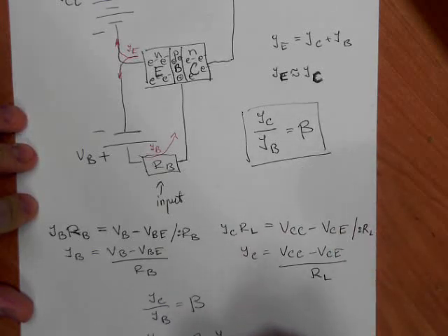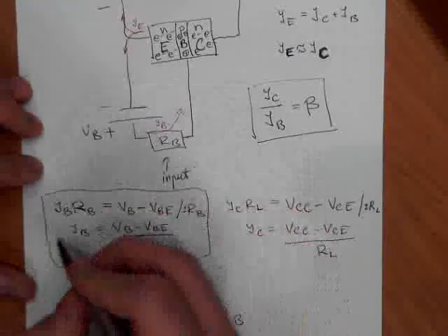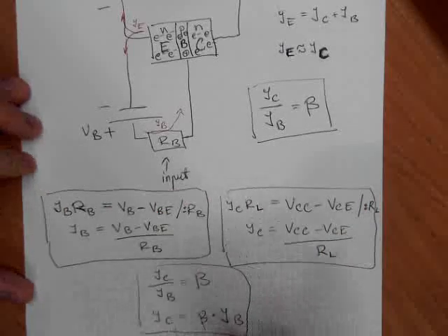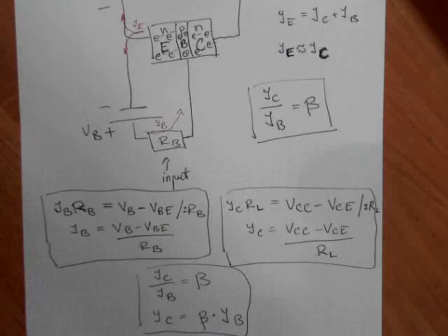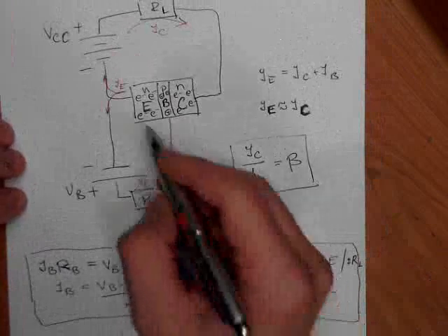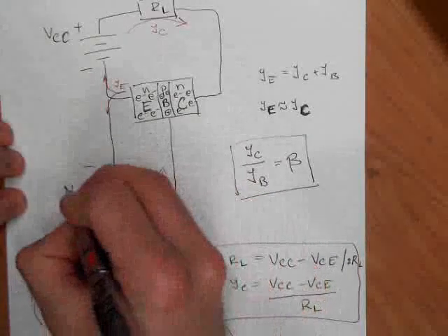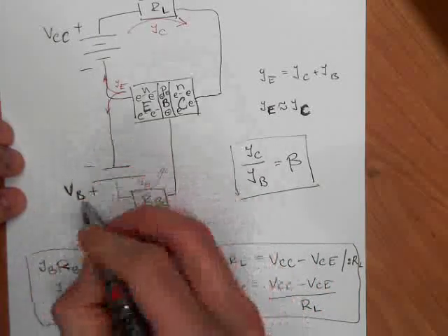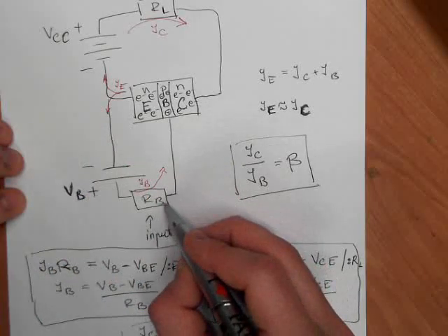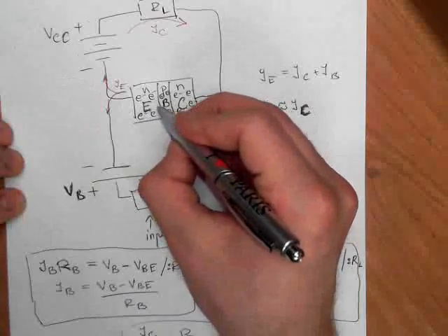So here you get three equations. Which first one is for what? It is for RB, for the lower circuit. This base voltage can drop only on two parts: on the base resistor, and on this emitter base junction. So it can drop either here or there.